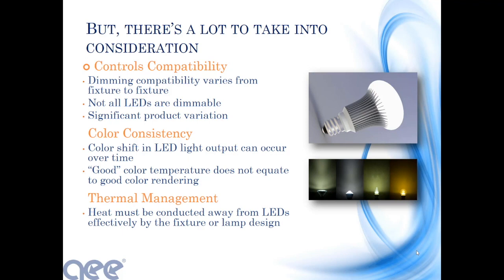And then the last of it, thermal management. We also talked about that as well because yes, LEDs generate less heat than a fluorescent. Why? Any engineers in the room? I squared R, right? If you have less watts, more efficacy, less watts, I squared R, less current, I squared R is your heat, less heat. So by definition, they put out less heat, but you still have to dissipate that heat in some way.